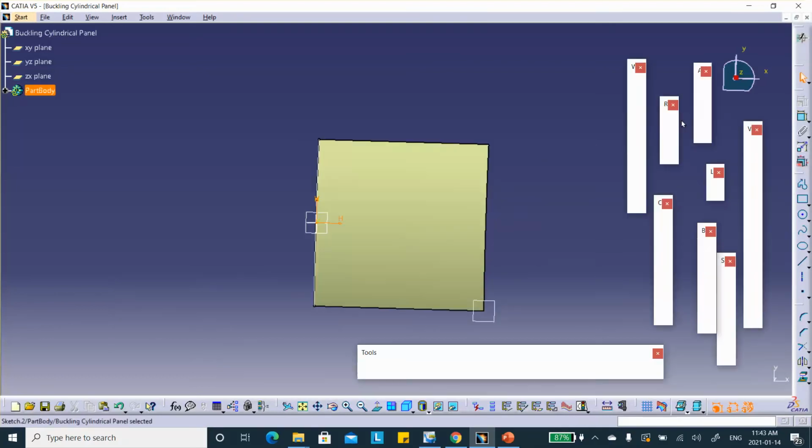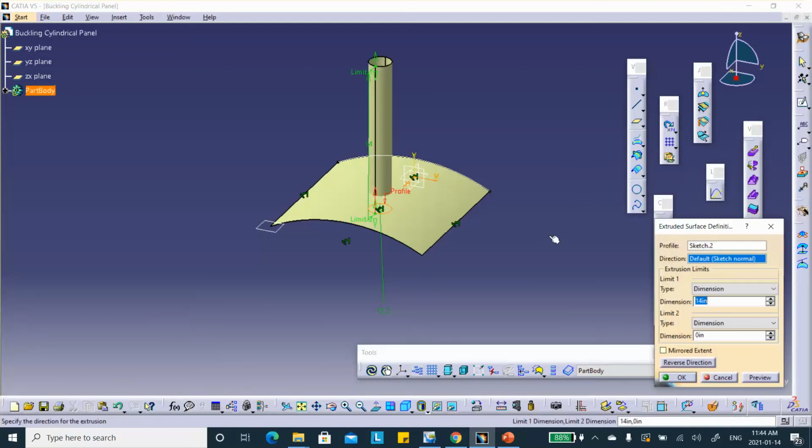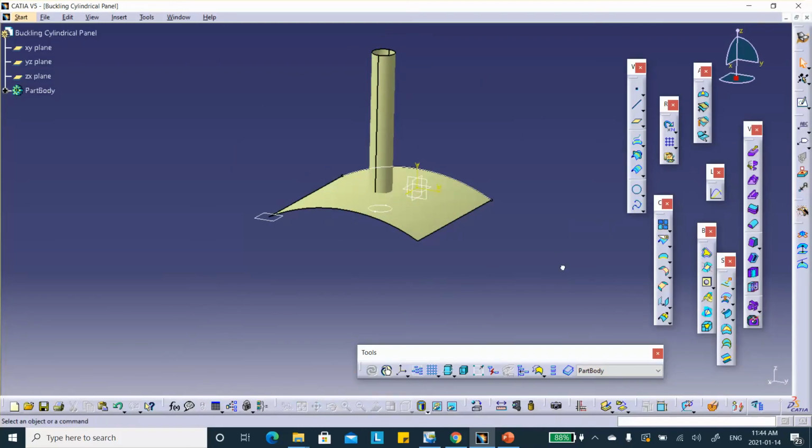You can do this any way you want. Basically, you have to create that panel with a hole. This is not the only way to do it, and not the best way of doing it, but I'll let you decide how you're going to do that problem. Now, one way of doing this is to extrude that circle, see that? Extrude it, and then we're going to split this surface with the other one. So let's see, we have split.